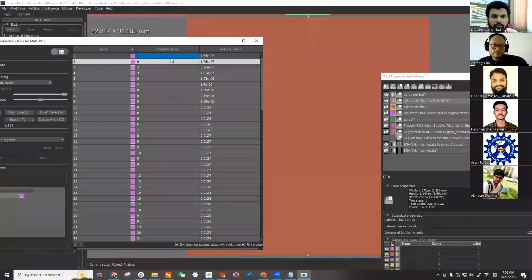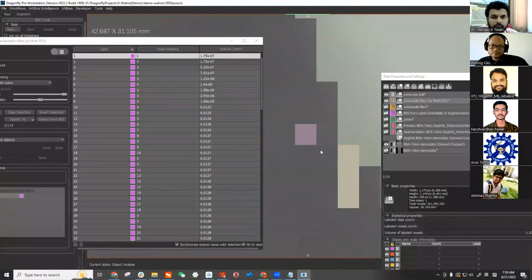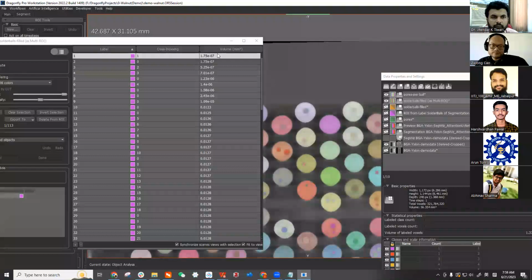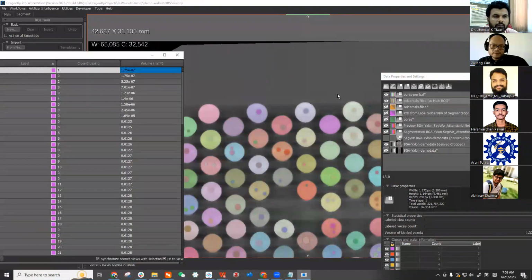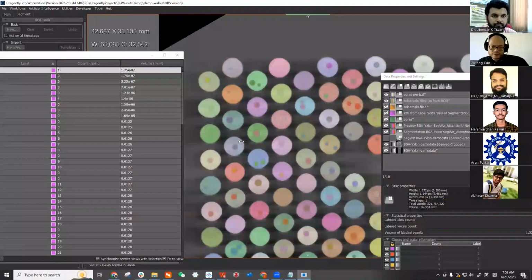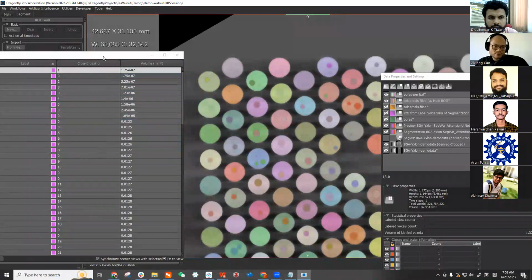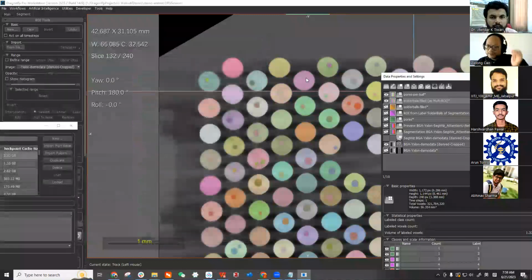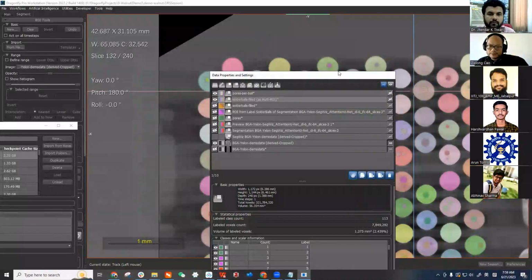If it's 1, it corresponds to the first labeled pore. And by doing some Excel analysis, you will be able to get a list of 113 solder balls and the porosity for each one. And this is a quantification.